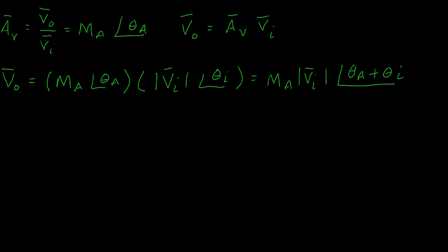Remember, what do we need to represent the signal in the time domain? Well, we need to know the magnitude or the amplitude of the signal. Well, here is the magnitude, the RMS value, right? And then we also have the phase here. And the frequency, again, as I've talked about, is understood. We know what the frequency is because we've worked the problem with a particular frequency on the input side. So we're going to be able to write V out. We have to find the amplitude, which is the RMS magnitude times the square root of 2.